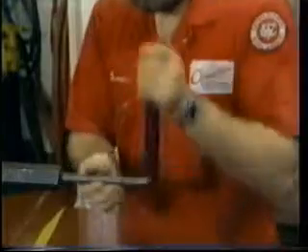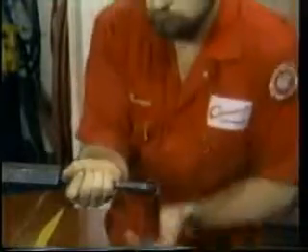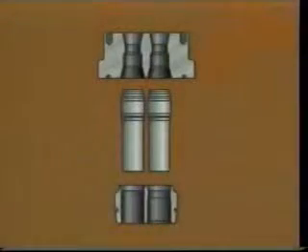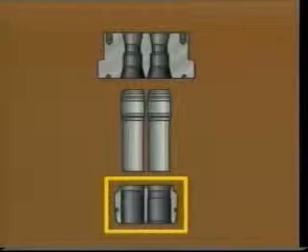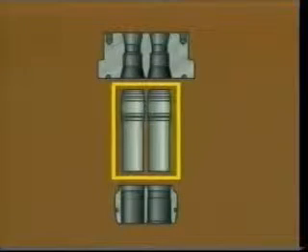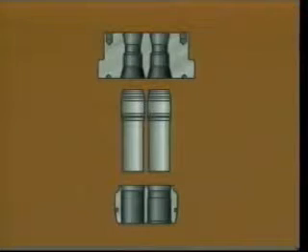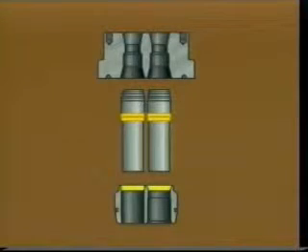Due to the increased clearance provided in this type of equipment, gas lift mandrels and downhole control lines can be run. The mandrel design includes a parent hanger that suspends two independent tubing hangers and provides the sealing of the ID of the tubing head bowl. The two independent hangers provide the seal between the OD and the parent hanger ID.